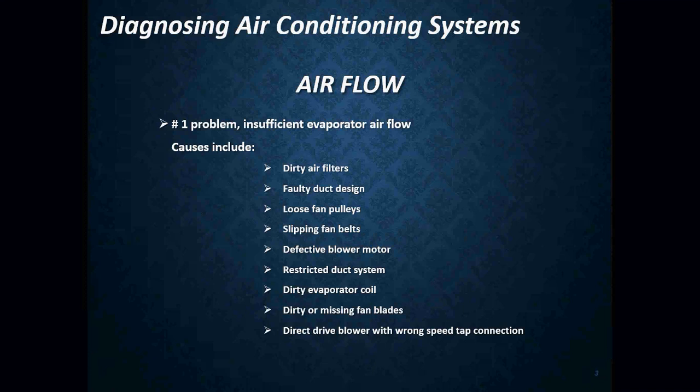Those motors will now ramp up in RPMs depending on the load in the system. And as the load starts to decrease inside the home or space, the blower motor will now start to lower its RPMs to keep and maintain the correct amount of CFMs based off of the demand in the house.